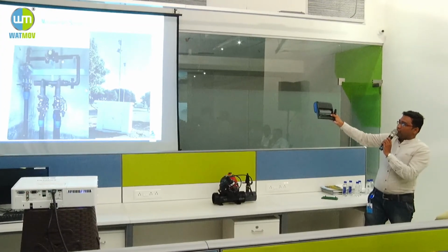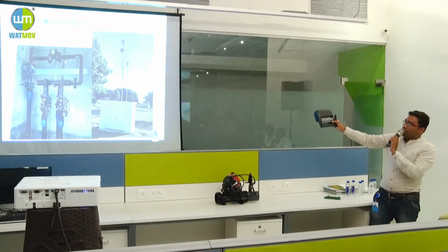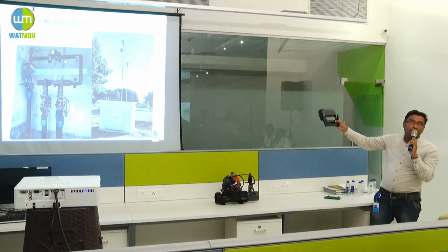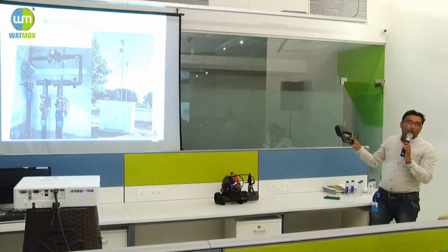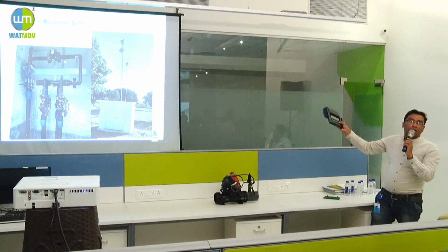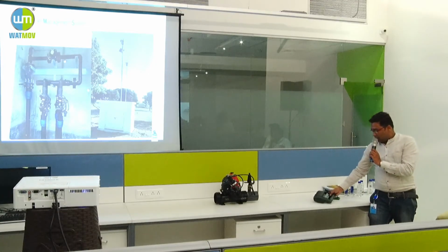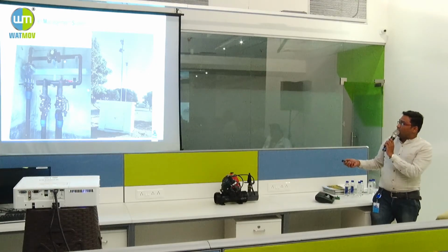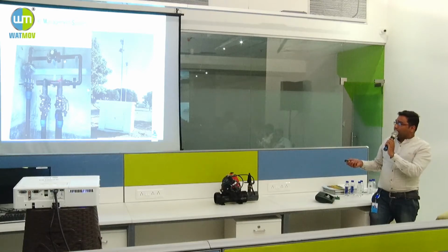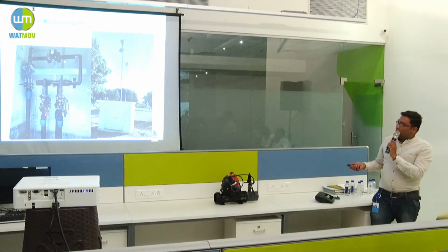So in OMS we take some inputs also, like an input from the water meter, its reading. This will go to the RTU and you can take the readings in your control center. Again, there will be a pressure transmitter mounted on this outlet manifold. It will sense the pressure, and again you can record this value in the control center. And the third function is to turn the valve on and off.